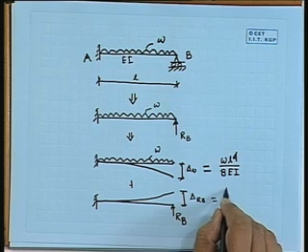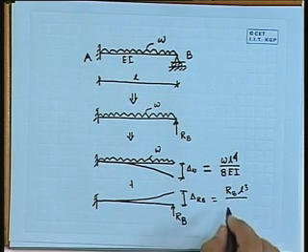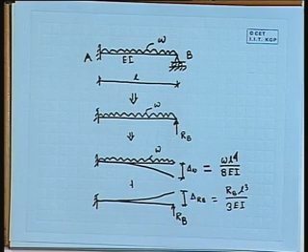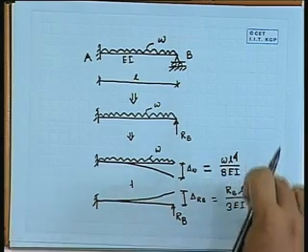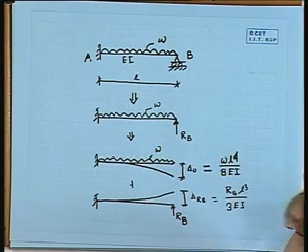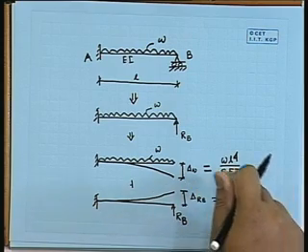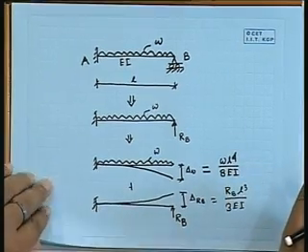Now, this force will be how much? It will be R_B L^3 divided by 3EI, right. Now, these two deflections should be equal and opposite. So, if we just equate these two equations, we can find out R_B in the form of W, L, E, I, something we will get from there. Okay. Now, next step, if we just equate that,